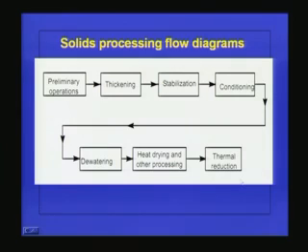That means we can go for different types of incineration processes, because we already have the sludge thickened, dewatered and dried. Either we can apply it to the land, and if you don't want to use that process and want to further reduce the volume, we have to go for thermal treatment or incineration, and various types of incinerators can be used for this purpose.